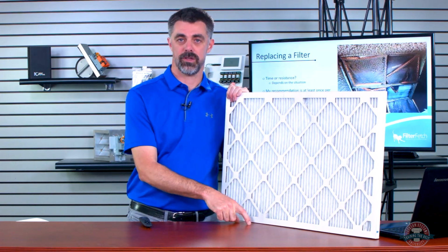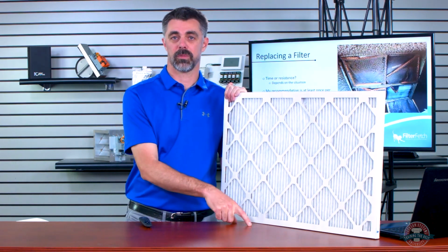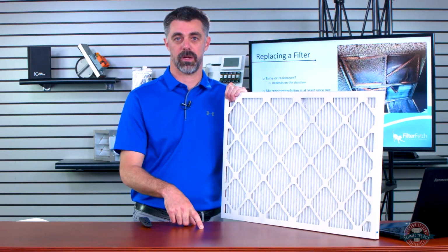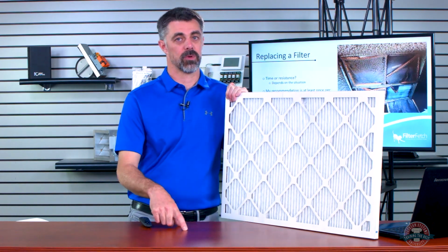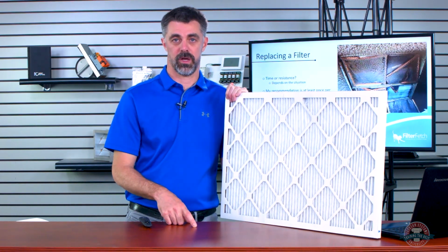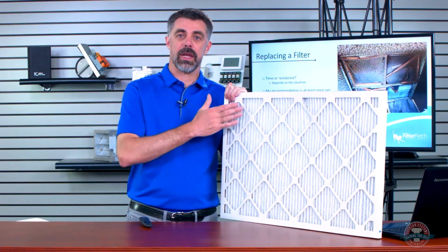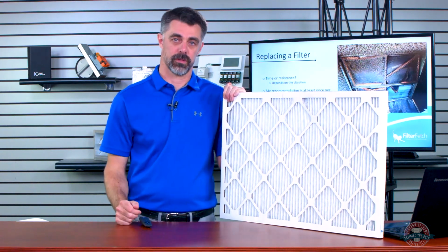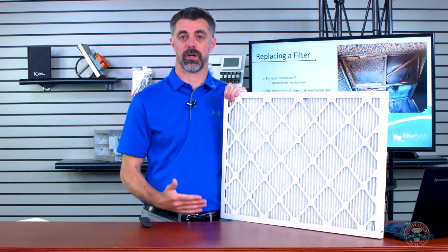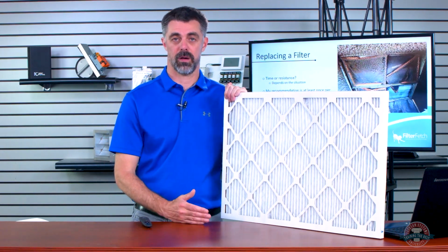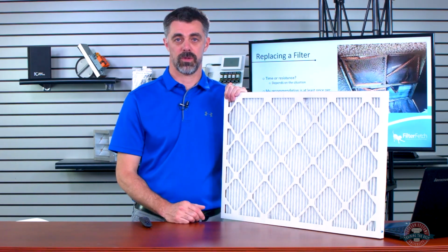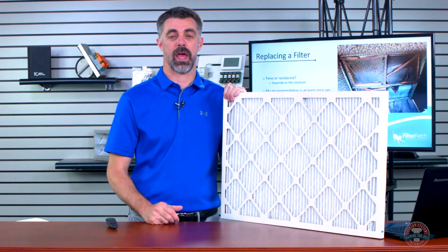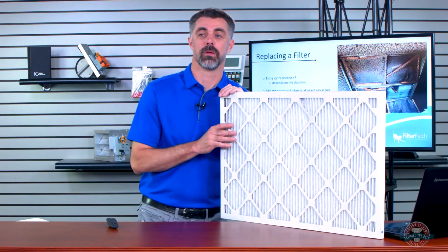And I recommend that they do that for a year, because if you're in the spring or fall, depending on what part of the country you're in or what climate you're in, maybe in the winter, maybe in the summer, you're not going to run your equipment nearly as much. So they need to get a good year's worth of data on it and then figure out how often they're going to change their filter. Or if it's a larger filter and a really clean house, it doesn't get that much dirt on it, have them change it once a year, maybe every 6 months when you're doing maintenance. It depends on how fast the filter gets dirty, really.